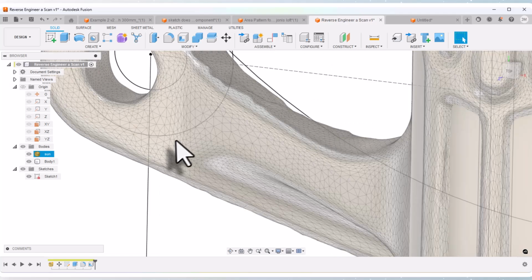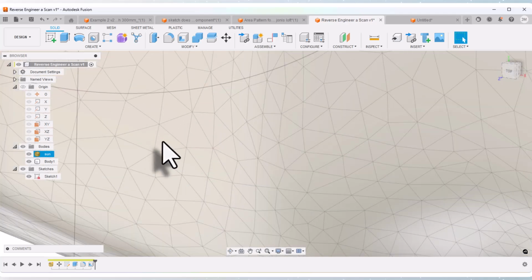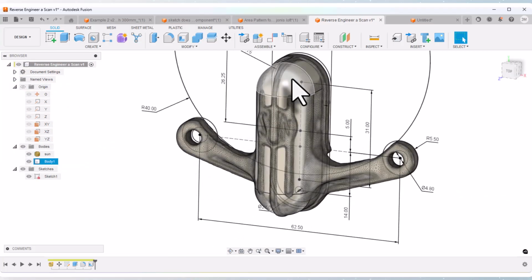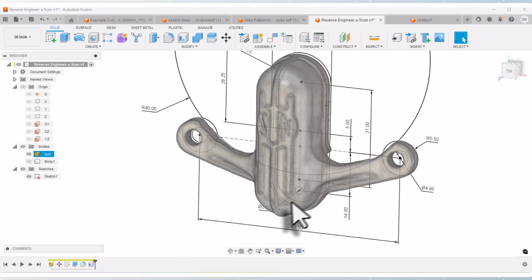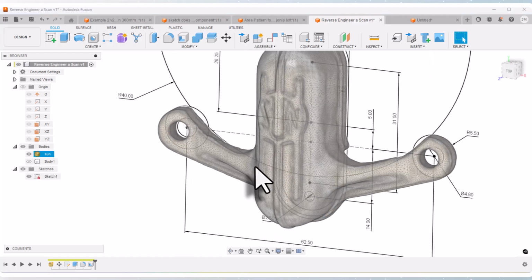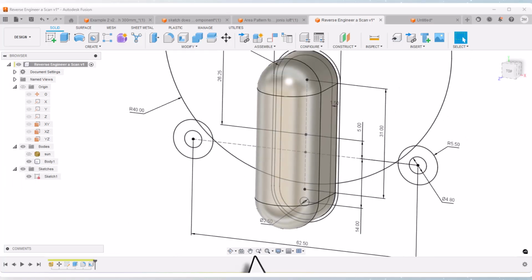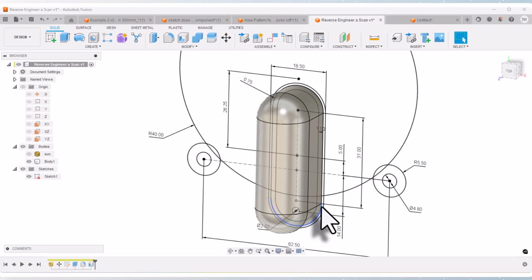If we look at this imported model, it is thousands of tiny triangular faces defined, outlined by straight lines. So when we zoom out, it looks like it's curved, but there aren't any curves in this geometry. It's all faceted triangular planar faces. So if we want true curved geometry, we're going to have to model that geometry from scratch, or at least from reference of the imported model.